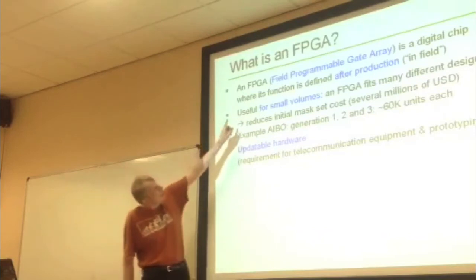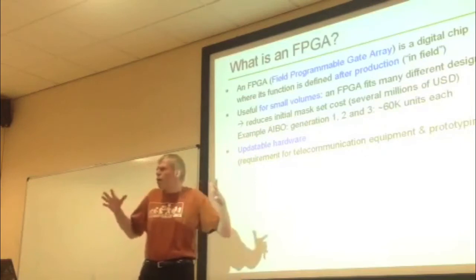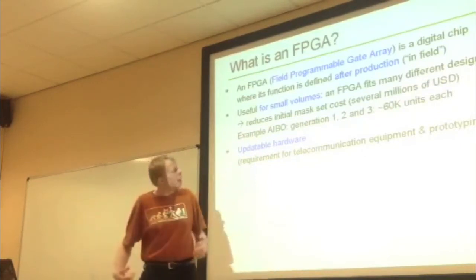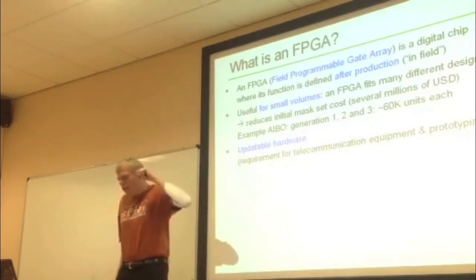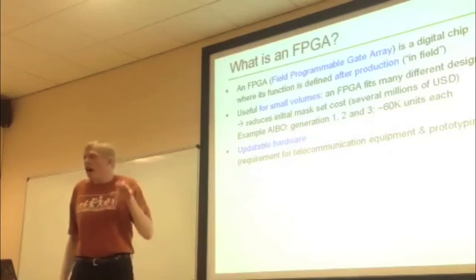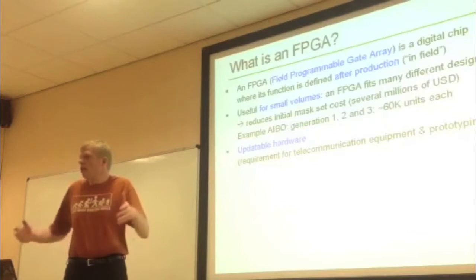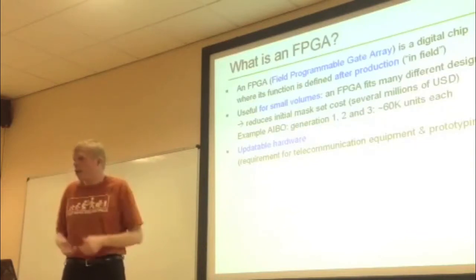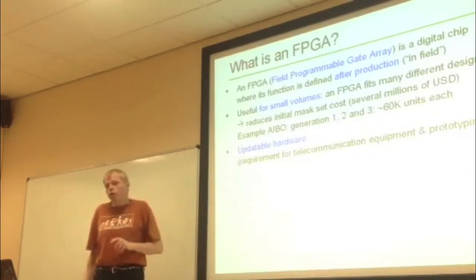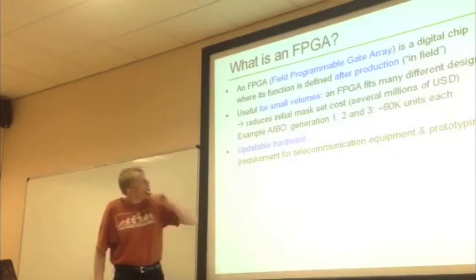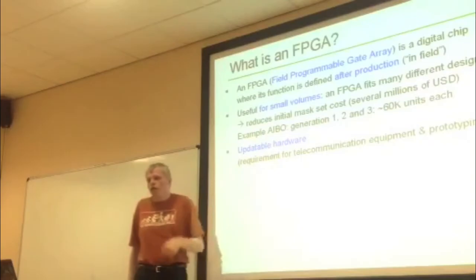First of all, FPGA is an abbreviation for field programmable gate array. Well, gate array you could imagine, it's an array of gates. Okay, what does field programmable mean? Field programmable means that you can define the functionality of this thing after production, in the field, on the customer side. It's not like Intel that produces an Atom processor and ships it to their customers, everything predefined. No, here you do this after production, to do the final customization. And it's useful for small volumes.